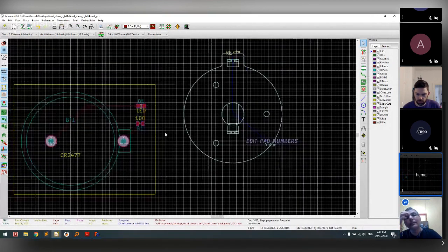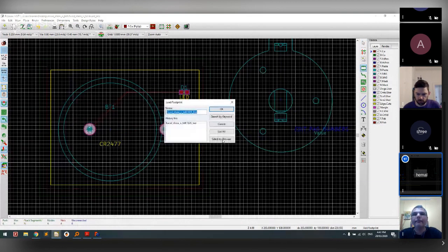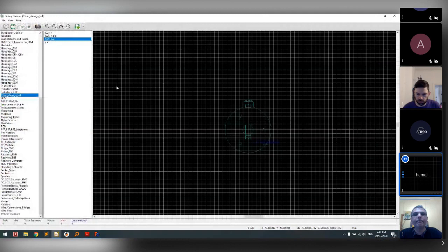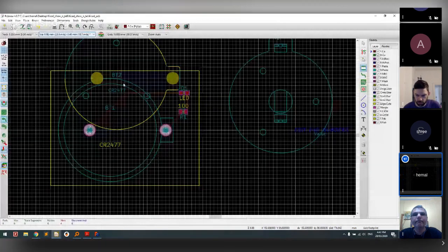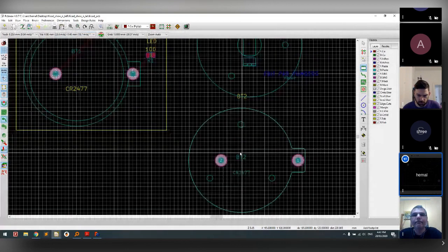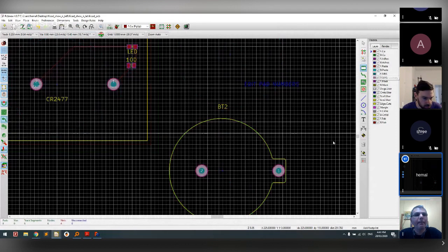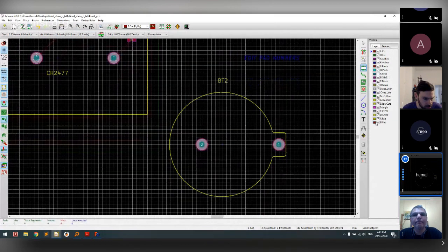The one that I used is this one. In this, I've also added the fab layer. Usually when I send for production, I always use a fab layer for the assembly house, because they will know the outline, and on the fab layer they will only have the references on the fab layer.